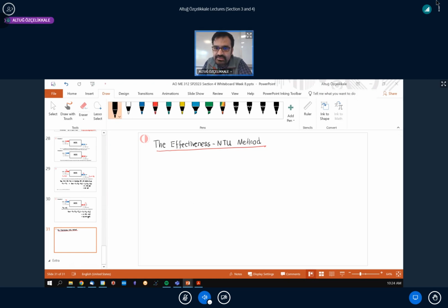We have already covered the maximum possible heat transfer, right? That is the heat transfer that occurs when we have a counterflow arrangement, because we have figured that a parallel flow arrangement is not going to allow this kind of behavior as the heat exchanger gets larger and the heat transfer area goes to infinity, right? These two conditions are going to maximize heat transfer.